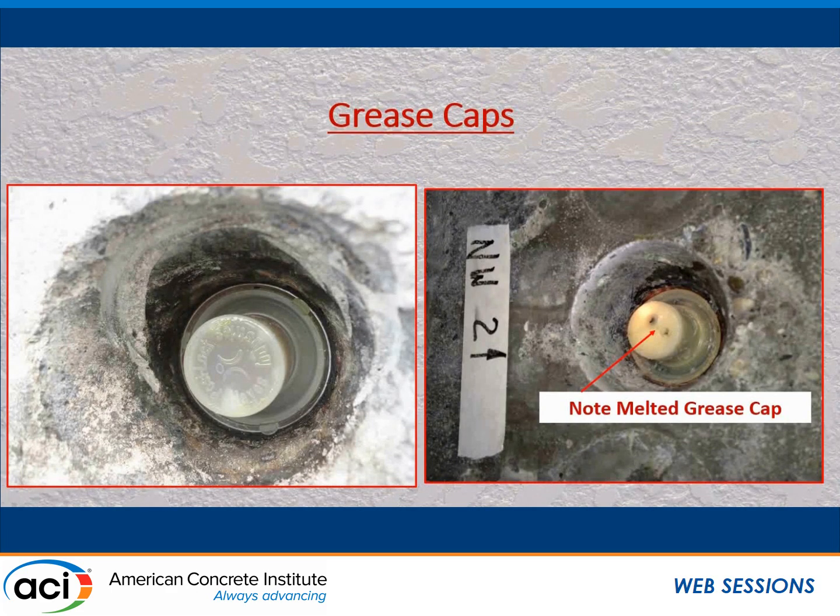And this was really interesting. The photo on the right was a part of this investigation, and those little black spots there, some guy was whacking those ends off with a torch, and he must have had his caps right there with him, and that cable was still 500 degrees, and he put it in there and it melted right through the ends of the caps. So we didn't find one of these, we found a bunch of them, and nobody on the team had ever seen this occur.